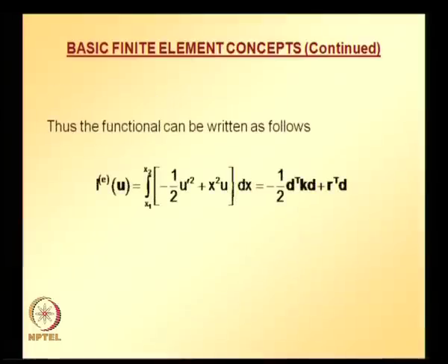So, you got the first term, you got the second term, you put them together. This is the equivalent functional for a typical element for which the boundary term, that is u at x is equal to 1, is not a part of it. For that kind of element, this is the equivalent functional, and now you apply the stationarity conditions to get element equations without boundary conditions.